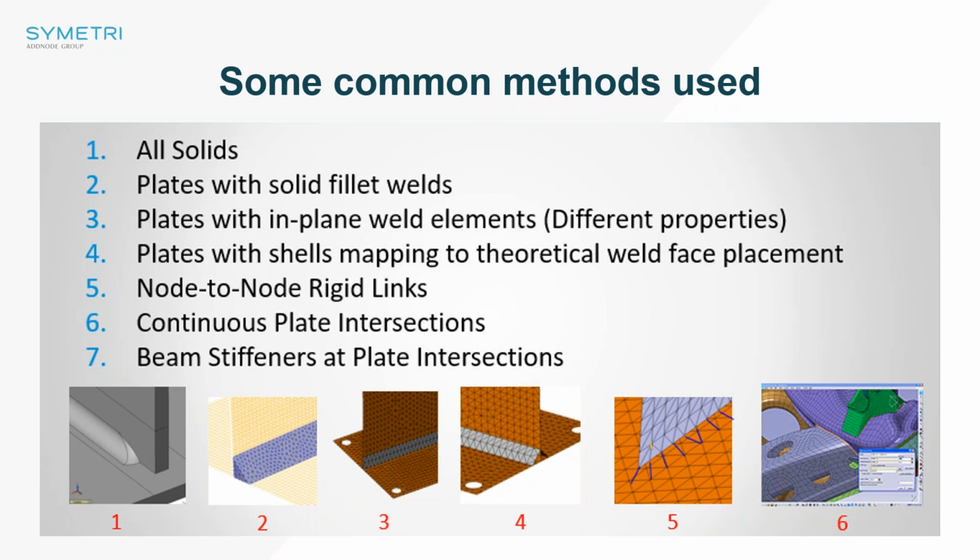And what you see on the screen is different ways companies have come across with methodologies and processes to simulate, well, that's the wrong word, not simulate welds, but to transfer loads via the welds, which have already been sized using some hand calculations, design codes, or some other mechanisms. And there is no hard and fast rule. Some companies will use solids, some will use shells with some solid fillets, as you see in example 2. And then you've got 3 and 4 using shells.